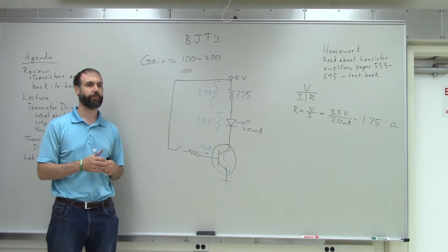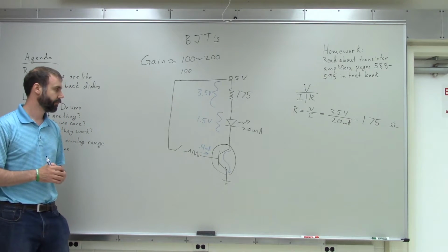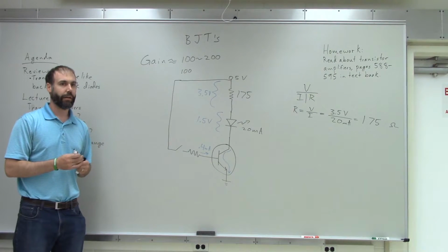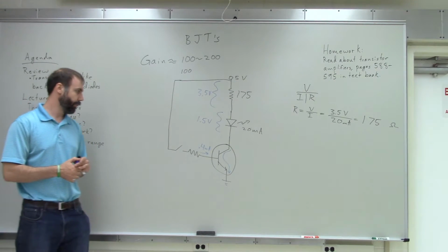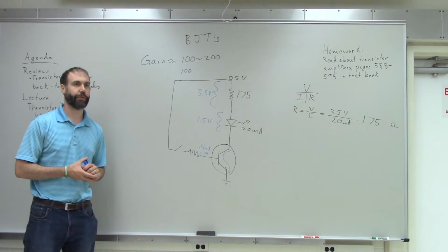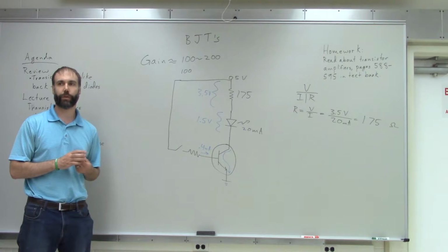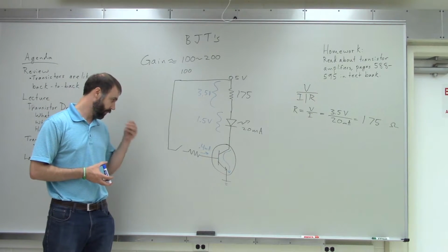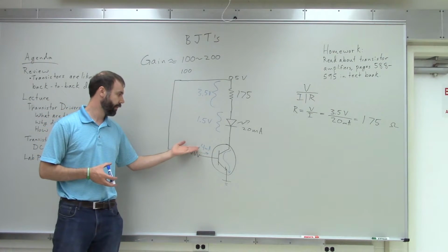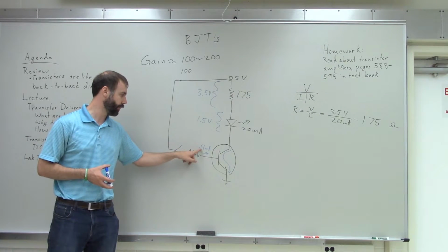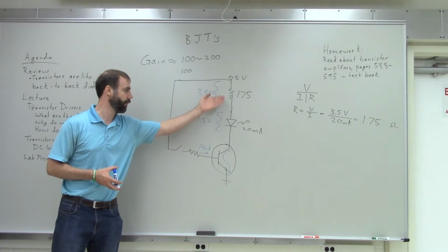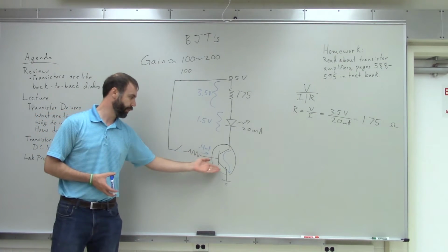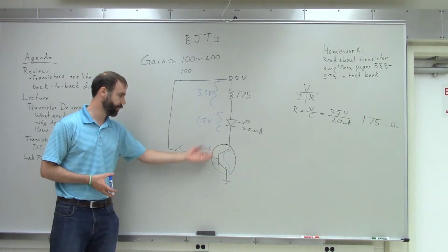Yeah. I'm assuming the max current is normally spec'd for the transistor, so you know how much more you can put through without blowing it up. Yes, exactly. So you would want to look at the data sheet for the transistor to make sure that you're within tolerance and within spec. But as long as you're within spec, you can just increase the current to more than your circuit would normally need, and then that'll make sure that the transistor is open extra wide.